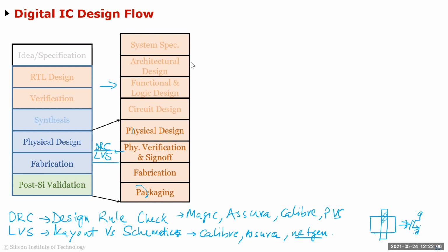It's just that if your design is digital and complex, then you want to do a semi-custom design, because otherwise it will take you forever to design that, right? If your design is simple or analog, for example, in analog there is no synthesis process, so you are doing full custom anyways, right? So you have to do that anyways.